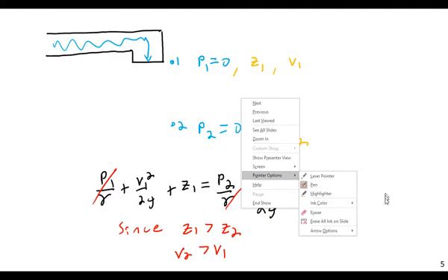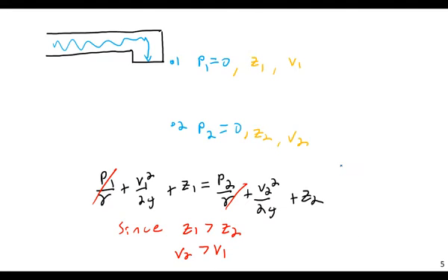But water, if it's at a relatively low velocity, likes to stick together. It's that surface tension thing. If it's not in a pipe, it'll actually kind of form a pipe of itself. It's just bound together by its own intermolecular forces. For a small enough flow rate, for a small enough diameter, for a low enough velocity, you've seen this. It will actually form a kind of shape all on its own, a sort of virtual pipe, held together by its own internal cohesive forces.